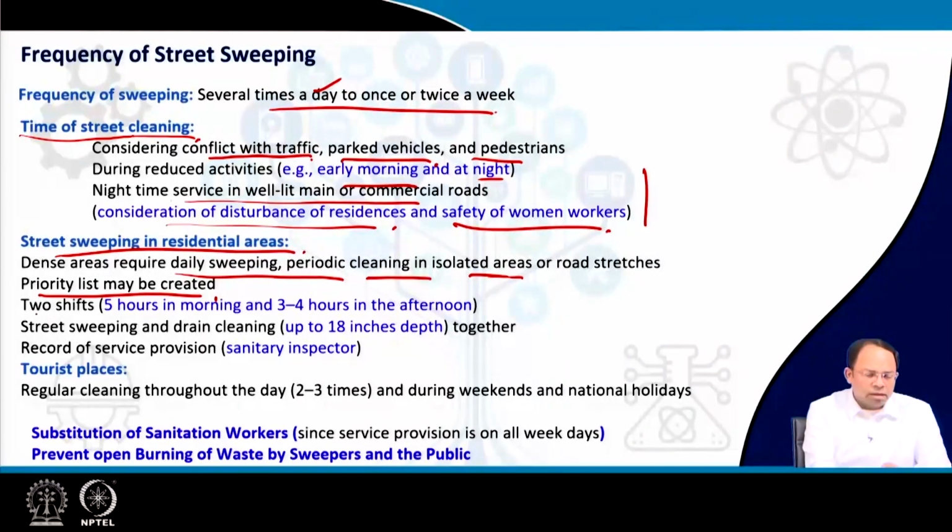streets. And there could be 2 shifts for cleaning, 5 hours in the morning and another 3 to 4 hours in the afternoon. In between you can give a break to your workers. Street sweeping and drain cleaning can be done together, particularly drains up to 18 inches depth could be taken care of by the street cleaning team.